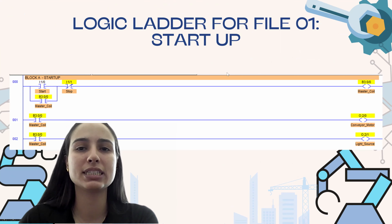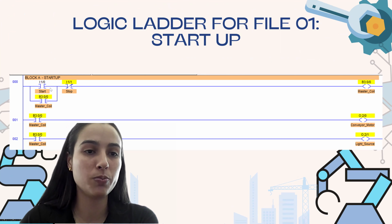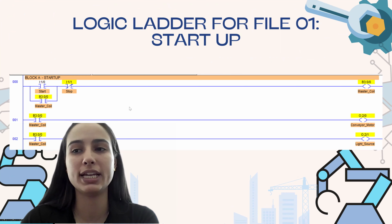Here is the startup block. In the file, I actually described the beginning as block A startup. Here I have my normally open start push button, which is parallel with the master coil to create a latch.